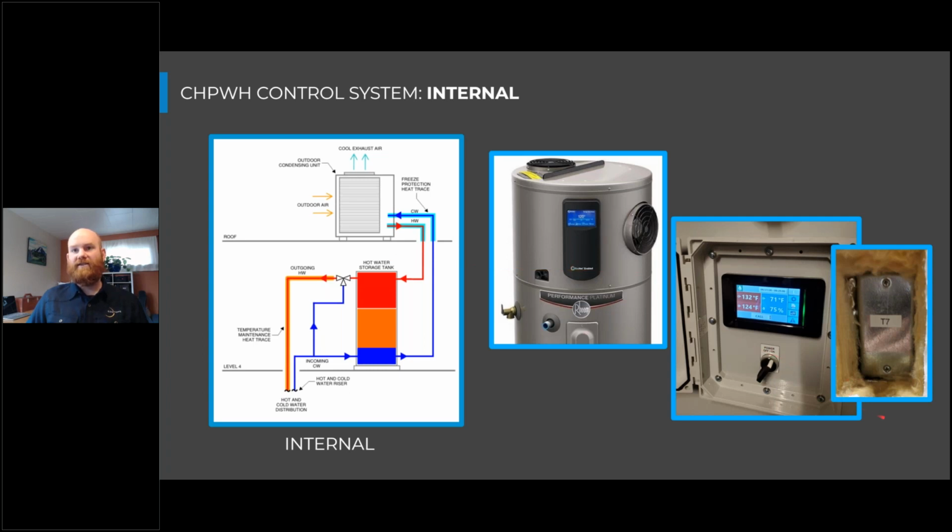In our larger systems, it's going to mimic this. Our larger commercial heat pumps are going to provide or have specifications on a certain temperature sensor that would be buried in a tank, and that's going to communicate with the internal controls to turn on and off that system based on domestic water load.